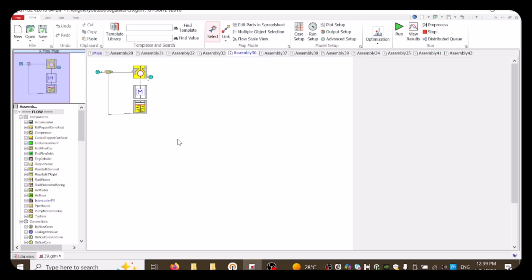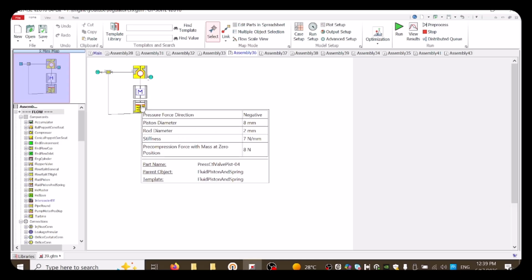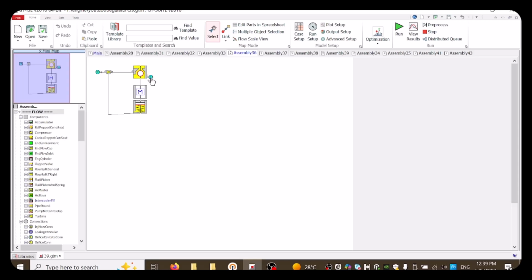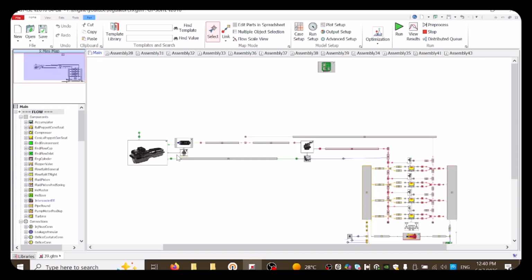This figure shows the pressure control regulator system. As illustrated, the regulator consists of an inlet valve, valve spring, a valve mass and a spring, and damper. Port 1 is connected to the outlet line of the low pressure pump, while port 2 is connected to the fuel bypass line returning to the tank.